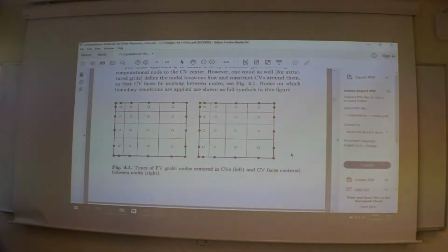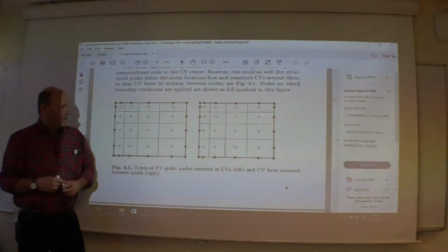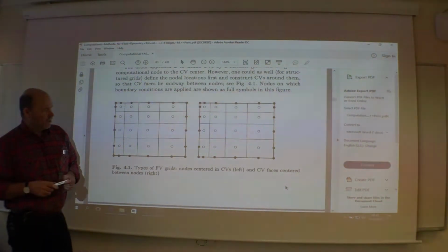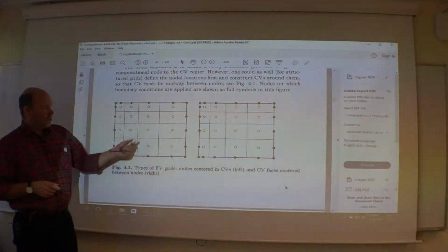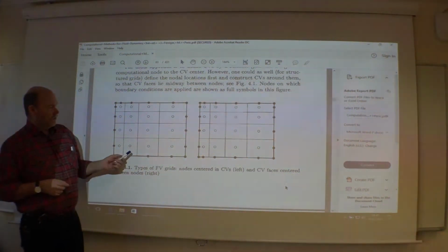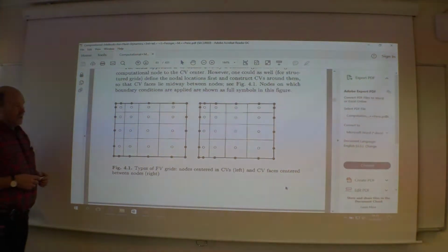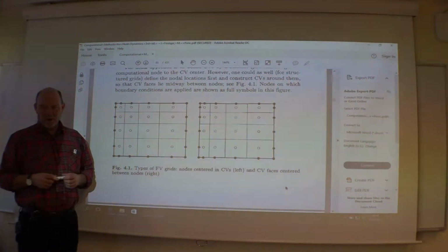So how to define your mesh system? You have a lot of choices here. Where should you put your unknown? Should you use a staggered mesh system like we had in SOLA, pressure in one point, velocities in different points, or like it's said here, a co-located mesh. You have all the unknowns in the center. That's quite popular these days. Much simpler, not so much bookkeeping.